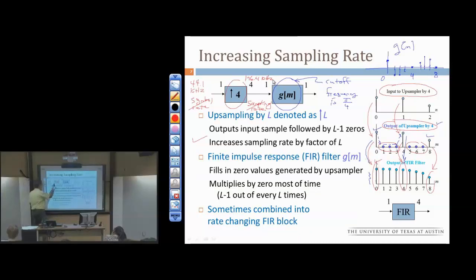But the original sampling rate means that I only capture frequencies below 22.05 kilohertz. This is the standard sampling theorem. So although I'm sampling at 176.4 kilohertz, any frequencies that are above 22.05 kilohertz are artificial. They weren't there. So this captures F max of 22.05 kilohertz. So where is F max here? Here's omega max.